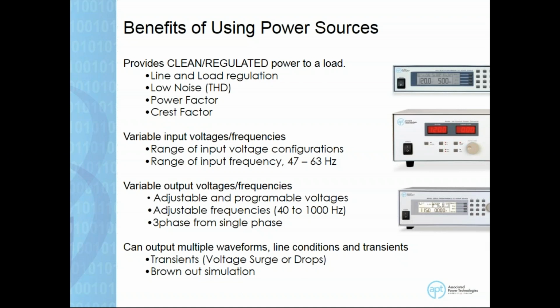So if I'm a design engineer and I expect my products to be anywhere from 0.7 to 0.9, and I'm running some tests on my products and I start seeing 0.5 as my power factor, I should be concerned because my design specification doesn't allow power factor to be below 0.7.